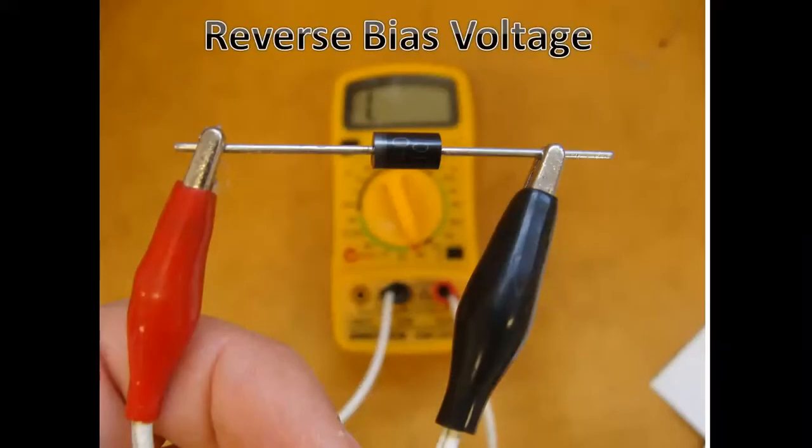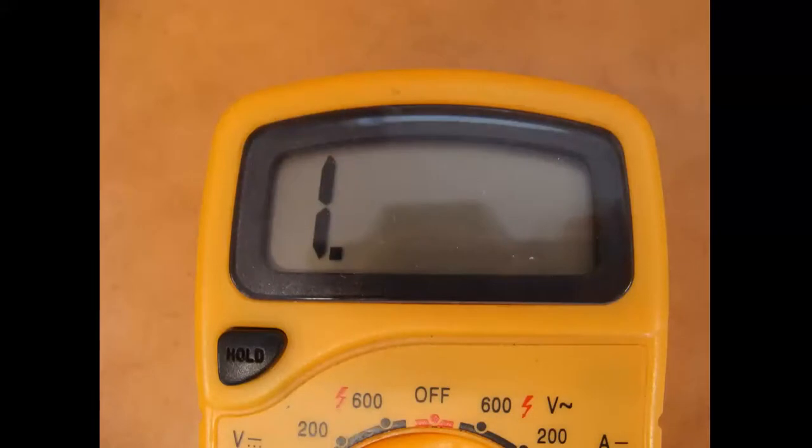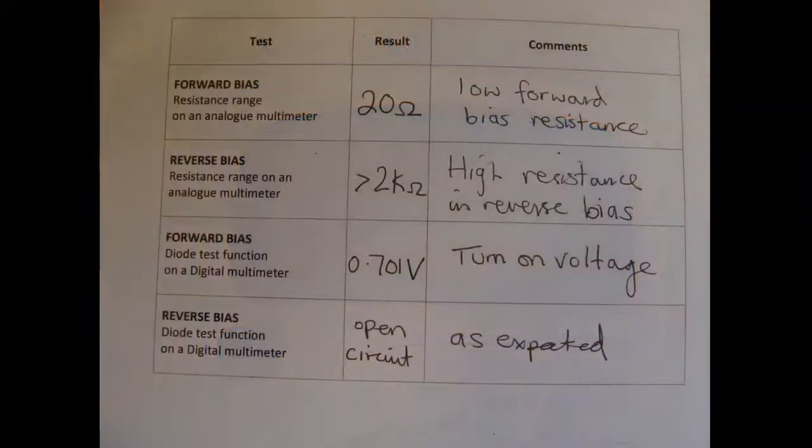The reverse bias voltage: if we put the positive on the cathode side, then we shouldn't get a connection. And so the meter reads 1. Now this 1 doesn't mean 1 volt or 1 ohm, it just means it's overscale, it's unable to read that voltage, and so it indicates an open circuit. And you're going to record those values there. So record the forward bias voltage, and then hopefully, unless your diode is faulty, you should get an open circuit, which is what we'd expect in reverse bias.